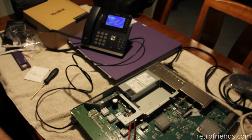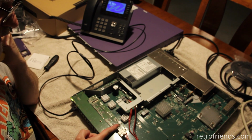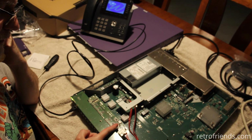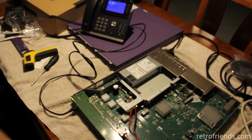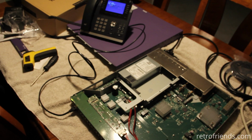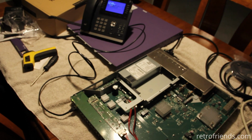So yeah, I believe that what happened is we had a diode that failed on the output. But yeah, I think we have fixed this switch. I think we just need to do a little more stress testing, probably do that at work where I've got multiple IP devices I can plug into it. But yeah, I'm just going to clean this up, put it back together, do some more testing and put it back into service.